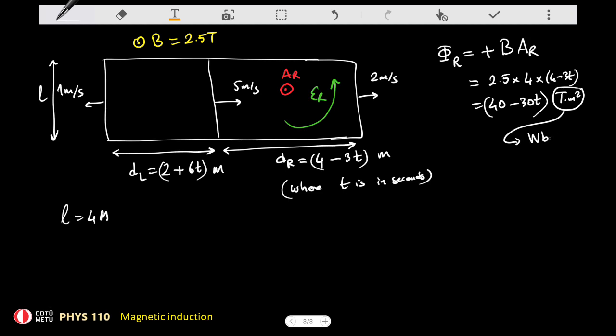In SI, of course, we also define this derived unit Weber. That's the same thing as Tesla meter squared. It's the unit of magnetic flux. So sometimes people also say that the Tesla unit, the magnetic field strength unit, is the flux density. So it's Weber per meter squared. But in any case, let's remember that the time derivative of the flux gives you the EMF, which has the unit of volts. So therefore, the flux unit also can be written as volts seconds. So sometimes you also see this unit used, but most of the time I'm going to use Tesla meter squared.